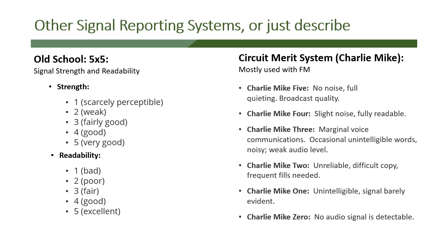And just so you know, what you're really rating on a repeater is the audio quality, not the signal strength, because essentially with the repeater, everybody gets the same signal strength because they're listening to the repeater. What you're really giving them is the audio quality coming into the repeater from their transmitting unit, because that's the part that's variable. Oh, you got a slight hum in your signal. Well, that's not from the repeater, that's from your side, because the repeater signal strength will always be the same because it's the repeater. Versus if you're running simplex, the signal strength will vary based on what station's listening to.